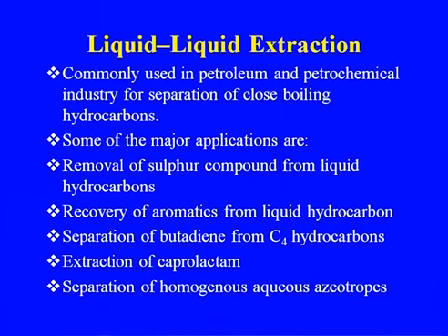Liquid liquid extraction is very commonly used in the petroleum and petrochemical industry for separation of close boiling hydrocarbons. Some of the major applications are removal of sulfur compounds from liquid hydrocarbons, recovery of aromatics from liquid hydrocarbons, separation of butadiene from C4 hydrocarbons, where the same problem of close boiling point components is there, extraction of caprolactam, and separation of homogeneous aqueous azeotropes. There has been continuous development in the solvents being used.